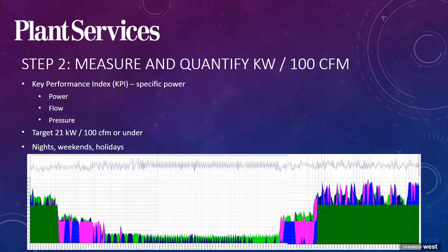Remember that since you pay for kilowatt hour, you should measure true power via kilowatt meters, which are going to monitor amperage, voltage, and power factor. Loggers should record data at least every second. This could or should be faster depending on the events you're actually measuring, but certainly you can look at data averaged over a preset recording interval, say 10 seconds, 20 seconds, but again, it's going to be determined by your plant demand.